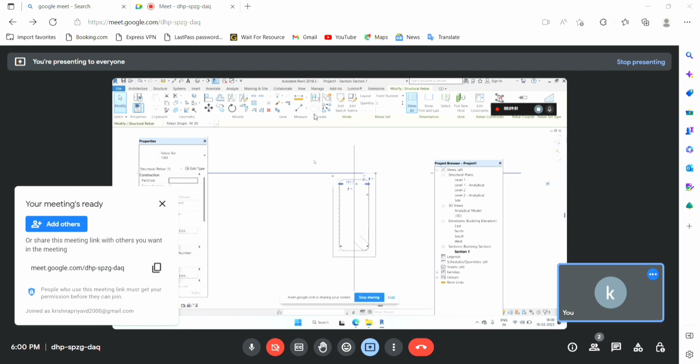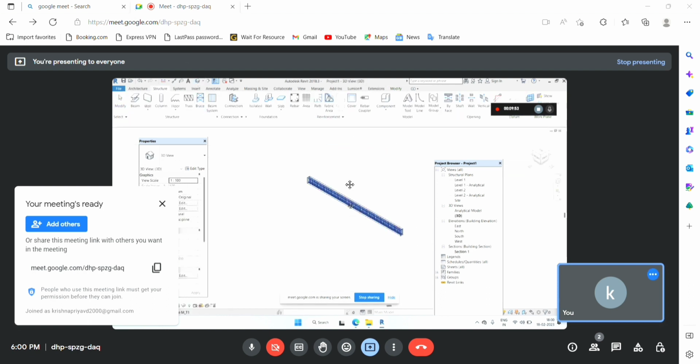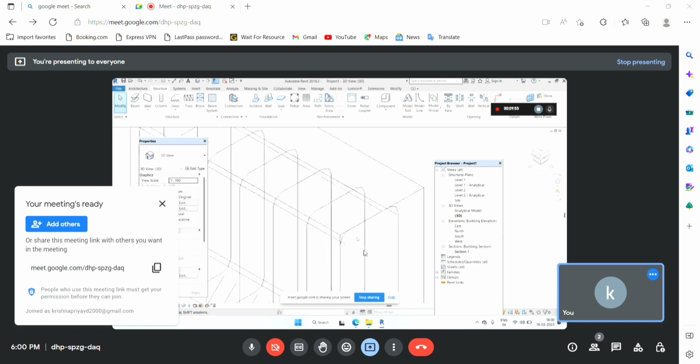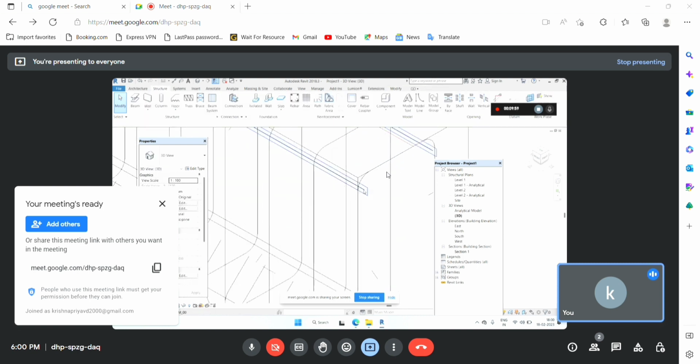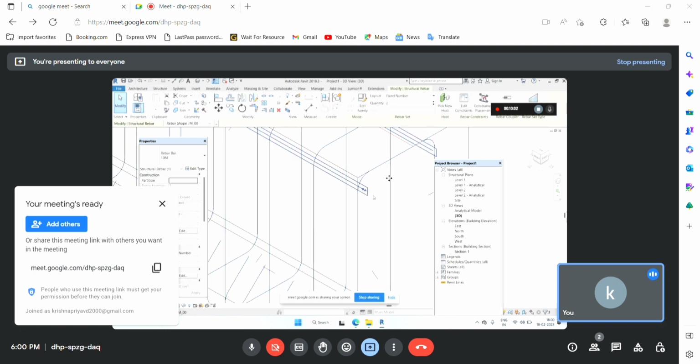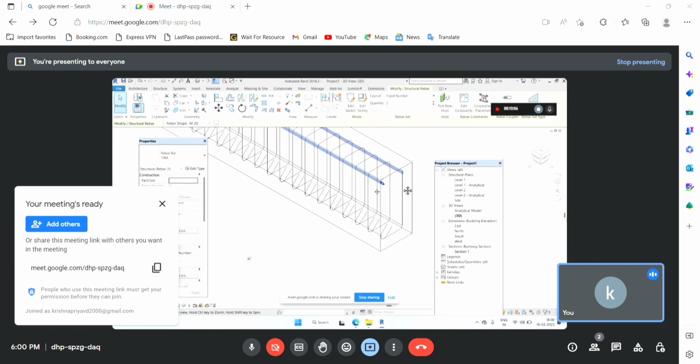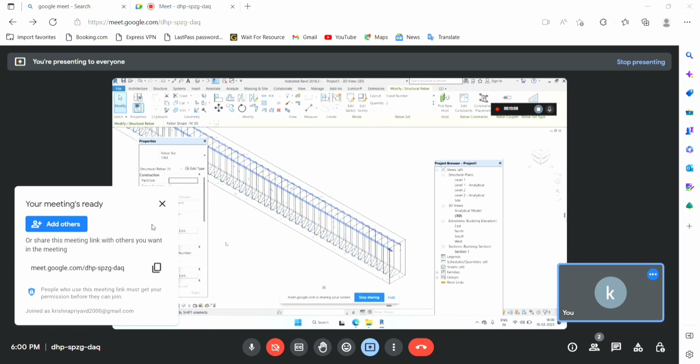And we can see the rebar here. So I want a hook bend diameter, a hook bend here. I just want to bend like this here and here. So I'm clicking the rebar. I just want to change hook at start to 90 degree and hook at end to standard 90 degree.